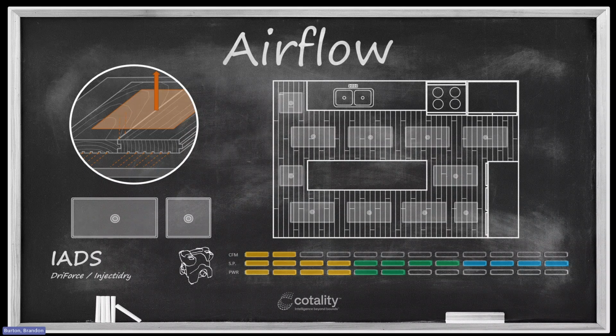The greater the opportunity for airflow, the tighter these mats can be to each other. The harder it is for the makeup air to get down between the boards, the further apart they should be. The closest I would ever install them is 2 to 2.5 feet. The furthest apart I would ever place them would be about 4.5 feet apart, depending upon how tight that installation is. Another way that you can gauge how tight the installation is, is by how much cupping has occurred.